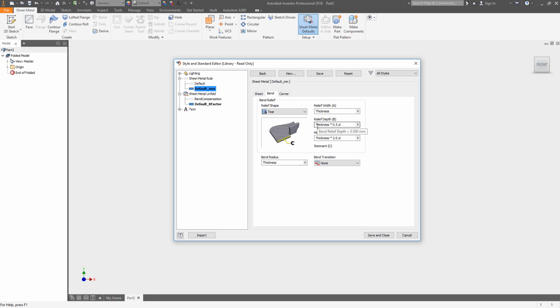As you're building this, this is why it's super important to know how your sheet metal is actually being cut and folded, because you could make a part inside of Inventor with sheet metal, and when you actually give it to them, it might not work and fit the default end folded product that you want it to be, because you have different relief shapes, different bend parameters, you're not following their bend table. So like I said, make sure you talk to the folks that are actually doing the fabrication of your sheet metal.